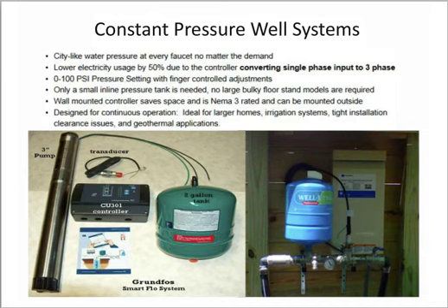So that well pump is actually down in its location in that well, and when the consumer opens up a tap or anything that causes the water pressure to drop, this control system will pick that up immediately, and it spools up that variable speed well pump immediately. And it's about the closest thing you're going to get to municipal water pressure. The typical well pump system, which we're going to get to in a moment, you'll actually have some variation in that pressure by typically 20 pounds, sometimes a little bit greater.